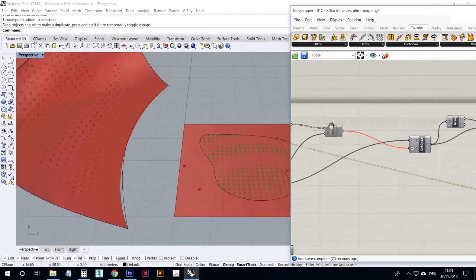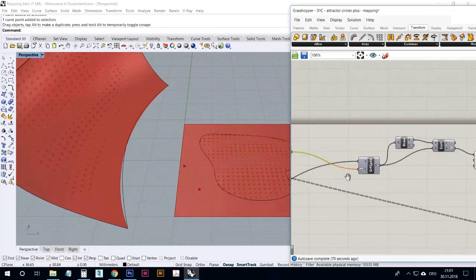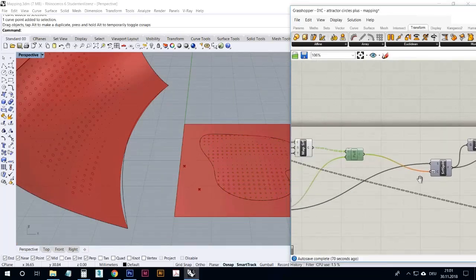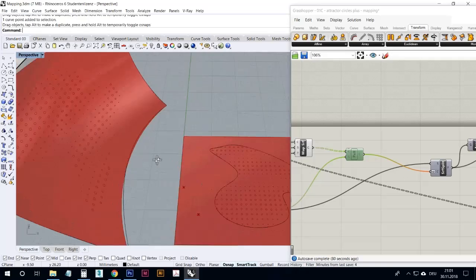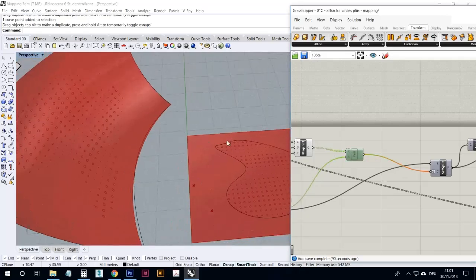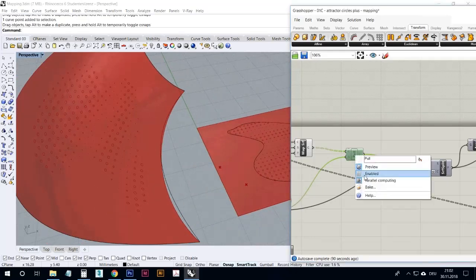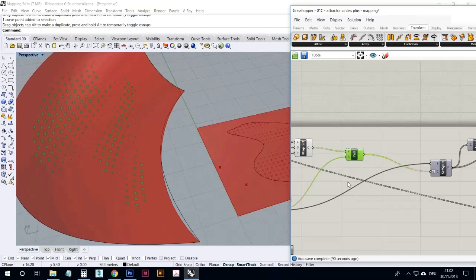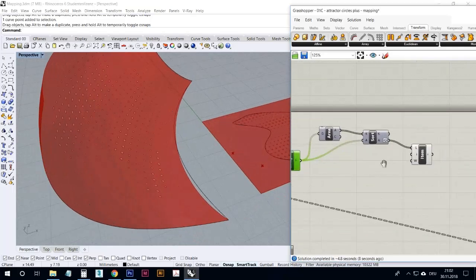After that, you can do split, which you see is disabled on that component. That's because it actually takes a lot of computer power. So when I start pulling around and changing, like changing this curve also, by the way, that will take a lot of computer power away. So that's why I leave it until I'm happy with the pattern. Then I turn it on, and we just wait a couple of seconds here, depending on your computer, of course, and then we will simply make a cut. So here you see the cut I just made, using also parametric components like these.